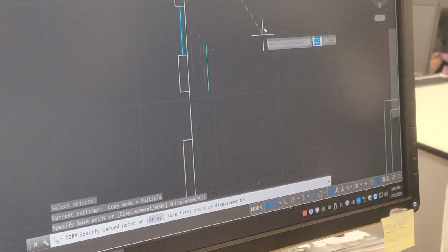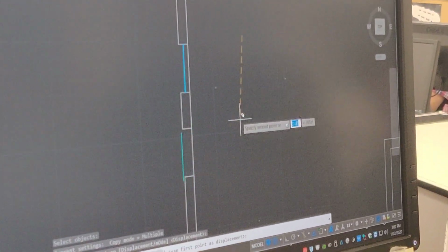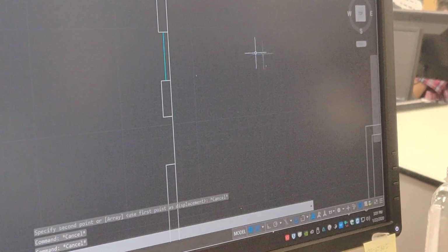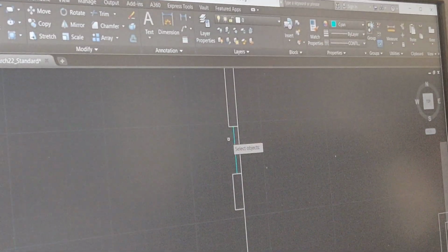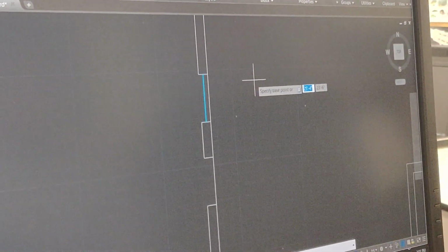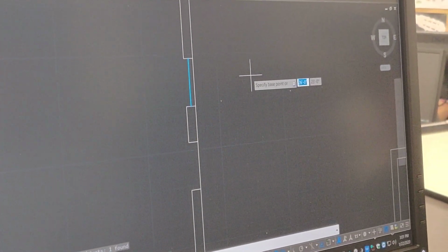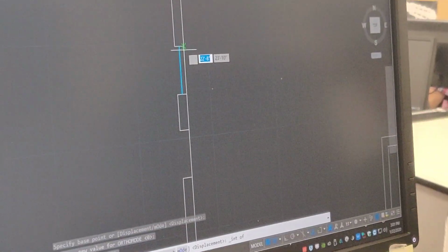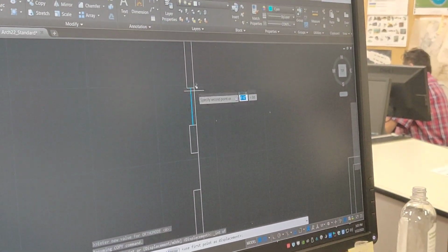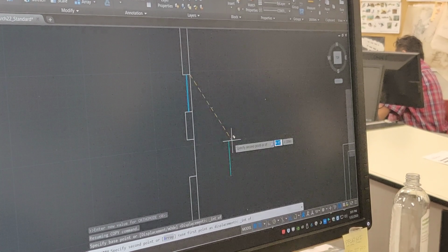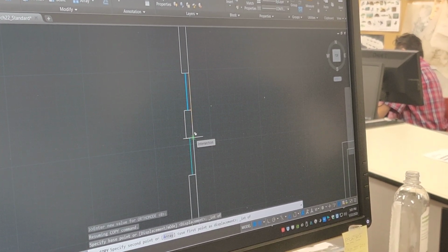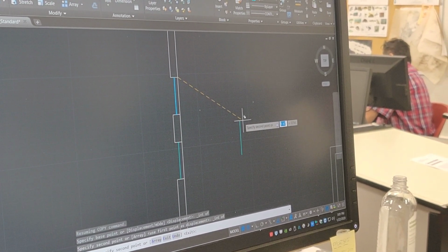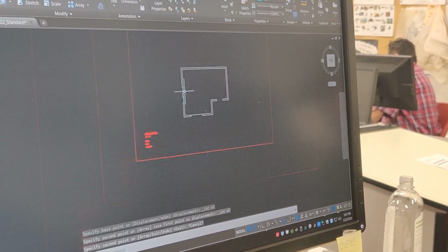Well, if I do this, now I'm trying to line that up, and it's a little tough to get right. Gosh, I just can't get it right on there. So I'm going to try this again. Copy. I'm going to select that guy. Right? Watch what I do. Again, shift, right mouse, and I'm going to go from the intersection here so I know I'm right at that intersection. And I'm going to go to the corresponding intersection right there. See that? So I know this is in the right location. Done. Hit escape, you're done.